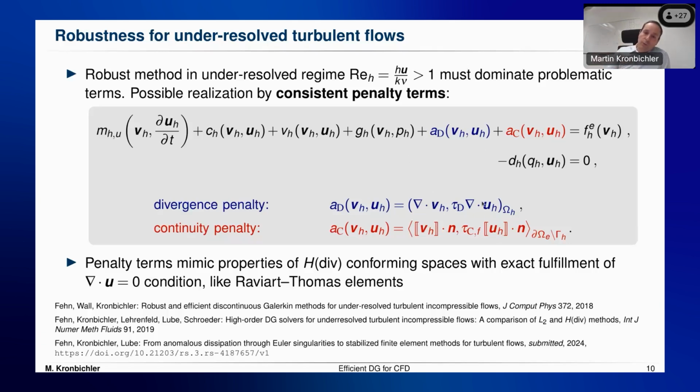So essentially, we're just getting rid of the discretization errors in the space. And we found in a paper when we compared the L2 method with the H-div method, so having this finite element space with the penalty factors, and the H-div method, that when you apply them to real turbulent simulations, we observed very similar results. So this was a good result.